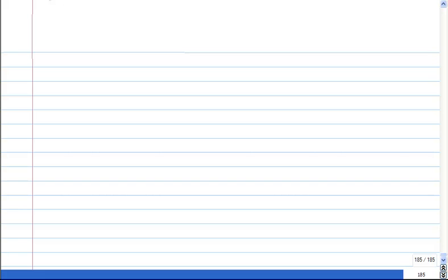That is the solution to the homogeneous part of it. And if you have a constant input, the steady state response is also a constant. And the total solution is the sum of steady state and natural response. The natural response is an exponential. The steady state response for a constant input is a constant. So combining these, you can find the total solution. And so the total response is the sum of steady state and natural responses.